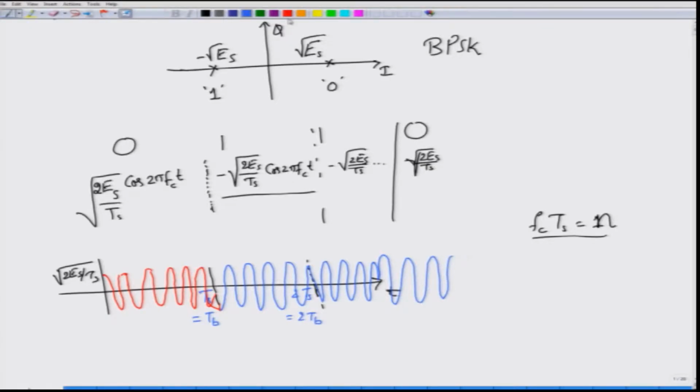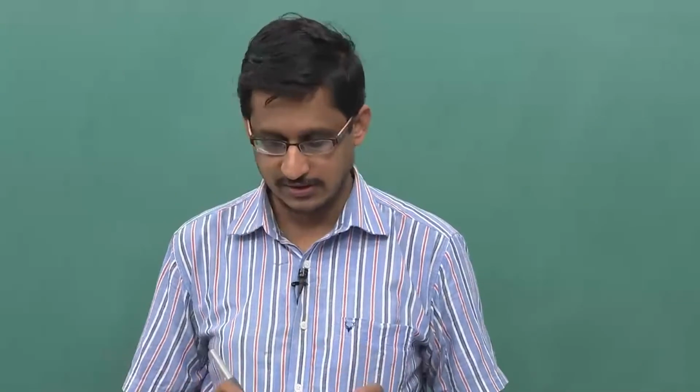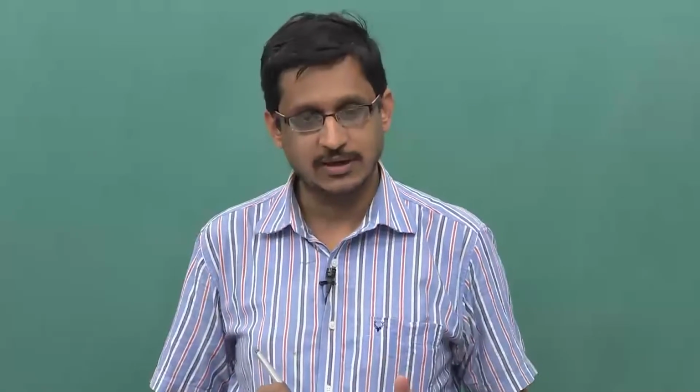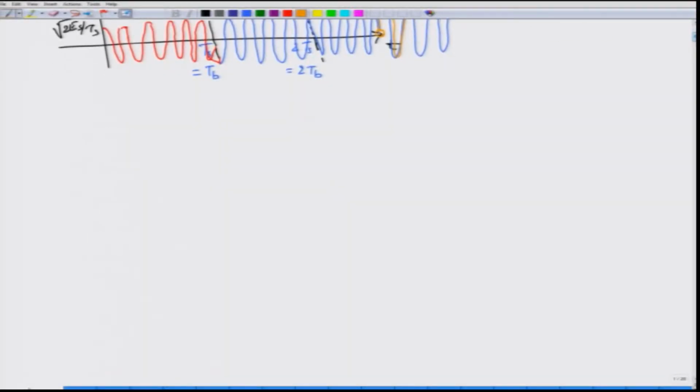Okay. So, if you notice here, at these points there is a change in the phase. So, at this point the phase goes from 180 degree to 0 degree. This sudden transition of the phase, from 0 to 180 degrees, is important, because these transitions represent the signal transitions or the phase transitions, right, corresponding to what sequence you are transmitting. And to implement this using an optical transmitter is quite simple.